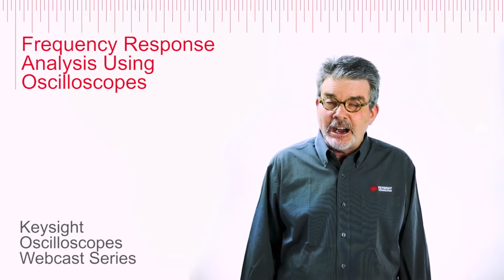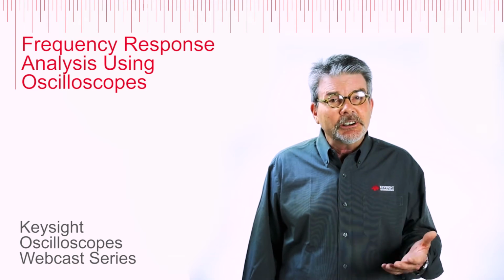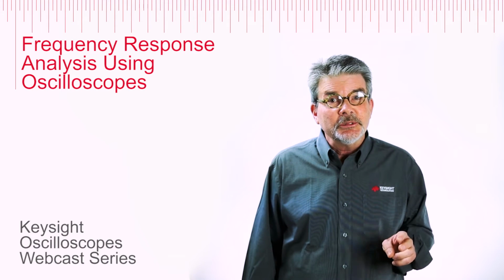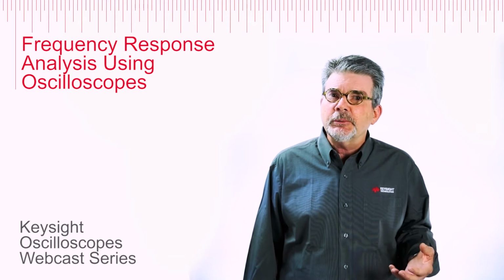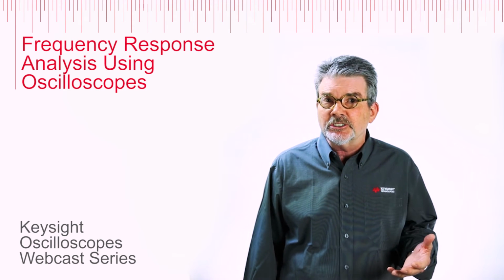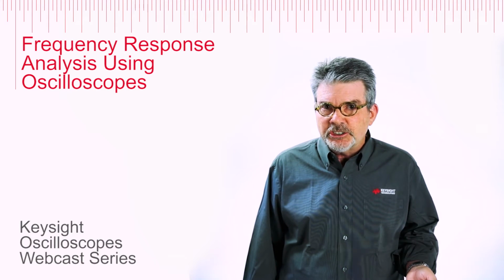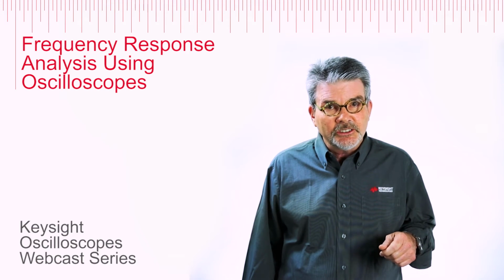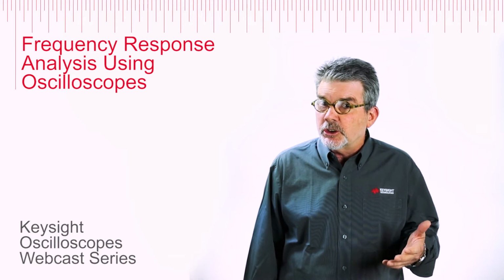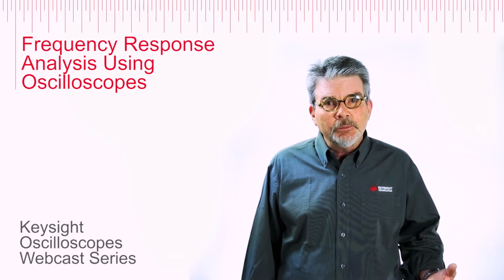Today, we're going to be talking about power supply frequency response measurements using an oscilloscope. Now, you typically use an oscilloscope for a broad range of power supply measurements, but there are a couple important measurements concerning frequency response where you typically have to turn to a frequency response analyzer or a network analyzer, which are specialized instruments. But today we're going to talk about those measurements, and specifically power supply rejection ratio, as well as control loop response, in other words, Bode, gain, and phase, and show you how they can be performed with an oscilloscope with a built-in source or waveform generator, and a special option that enables it to do all of this automatically.